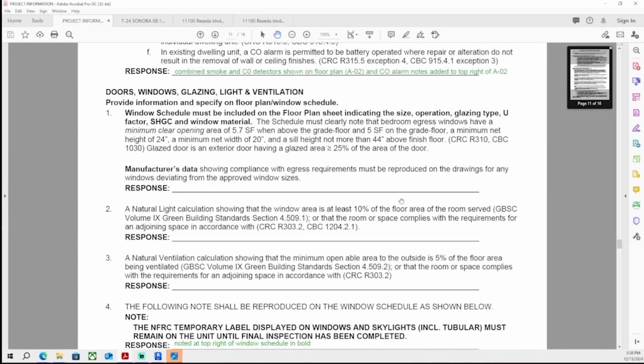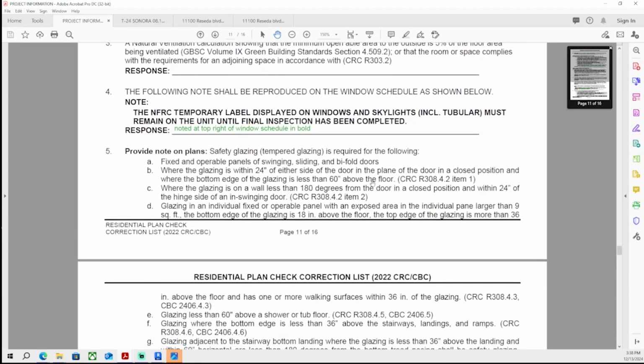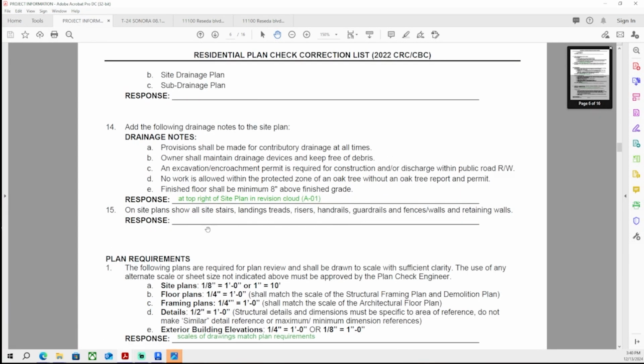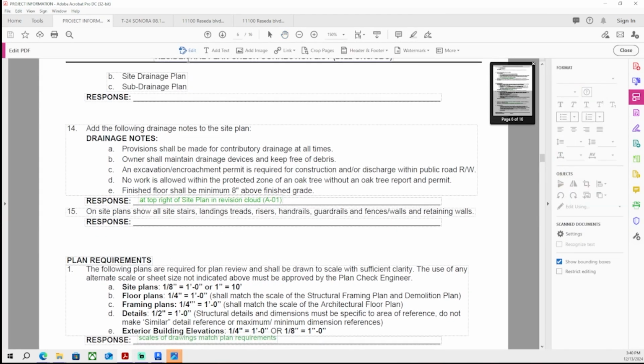But a lot of jurisdictions, you can get drawings approved without even showing your gutters and downspouts, because that's something the contractor will put in. But maybe it's good to see them on the plan, so you make sure it's in a place where it doesn't conflict with the water heater, the air conditioning unit that's outside, or any landings. And maybe you can make sure that the water gets into the landscaping.